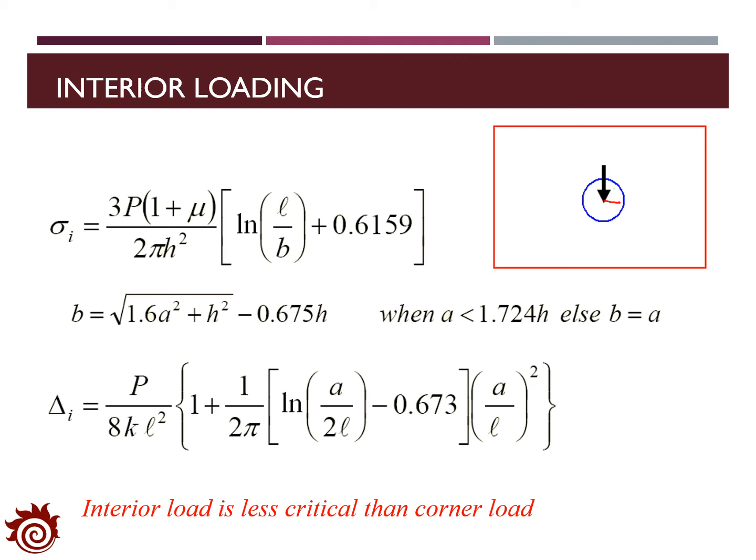The contact area is a circle with the radius of a, and the load is set as P. With these settings, we can find out the maximum stress by the first equation, which is a function of the load, Poisson's ratio, thickness of the slab, and the radius of relative stiffness. There's a new variable b, which is a function of the radius and the thickness.